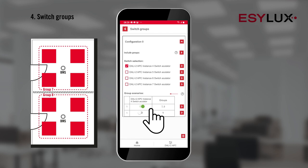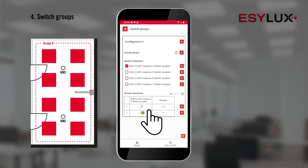When the partition is closed, groups 7 and 8 are enabled, and the detectors work independently of each other. Opening the partition activates group 9, and the detectors work together again.